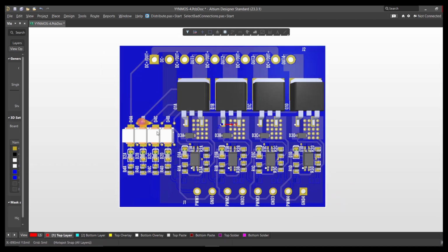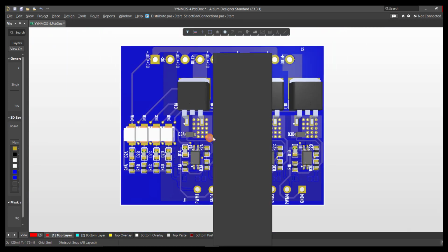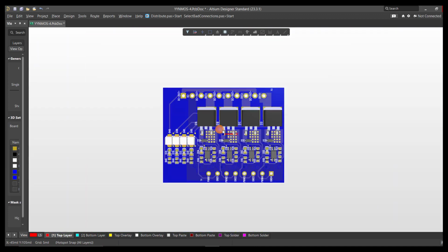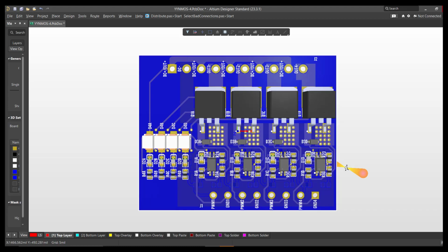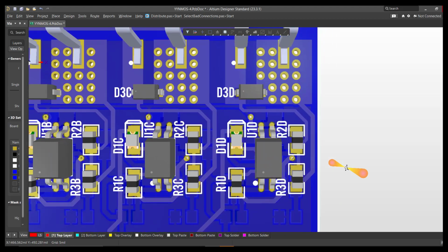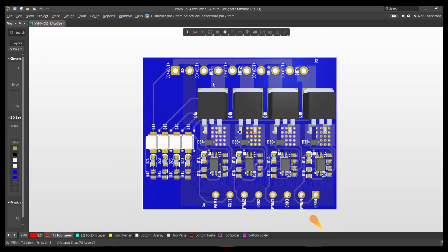Next is navigating a PCB 3D View Layout Mode. Within the PCB editor's 3D Layout Mode, you have the flexibility to zoom, rotate, and navigate through the board using a combination of keyboard and mouse controls. To zoom in on the board, simply press and hold the Control key on the keyboard and simultaneously right-click, then gradually move the mouse upward. Conversely, to zoom out, move the mouse downward while holding the Control key and right-clicking the mouse.